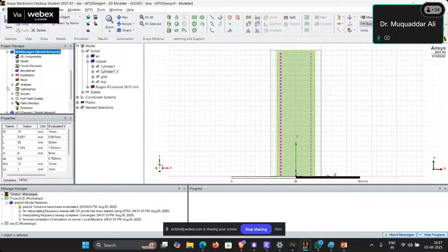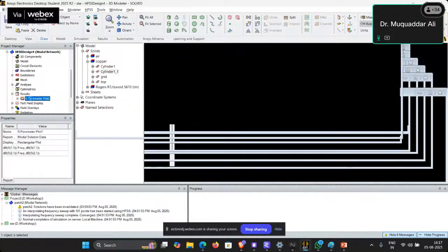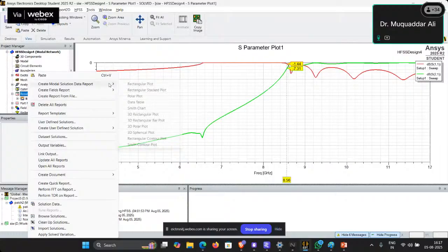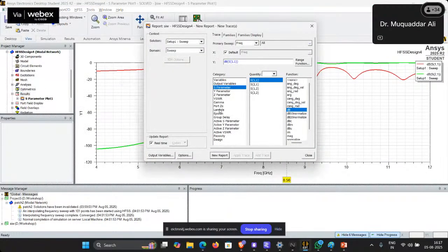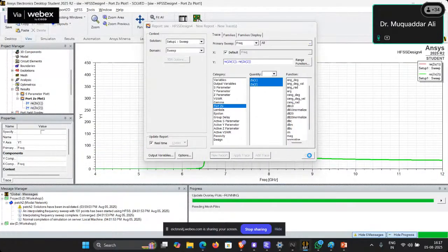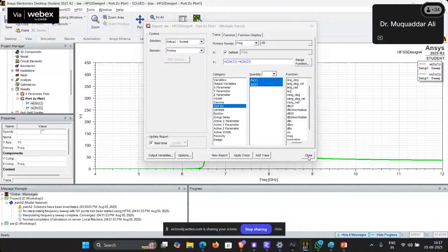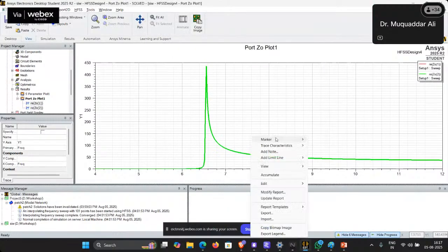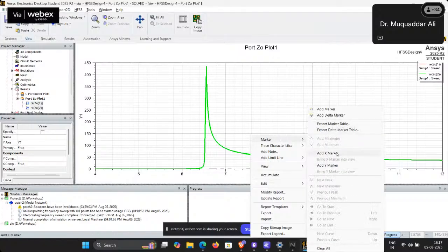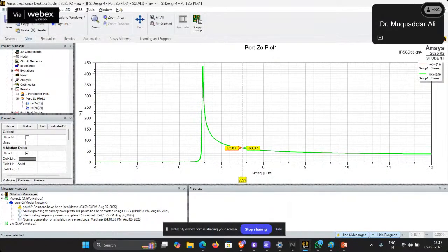If we check the impedance of these wave ports at port 1 and port 2, at both the ports we observe that our SIW has a higher impedance, 61 ohm, whereas our feeding network will have an impedance of 50 ohm.